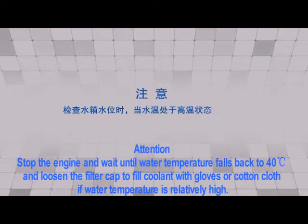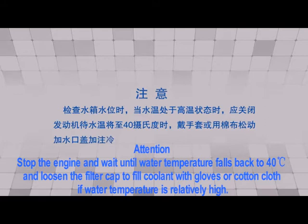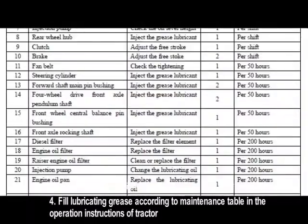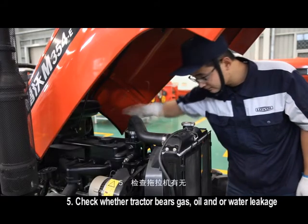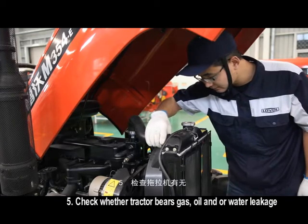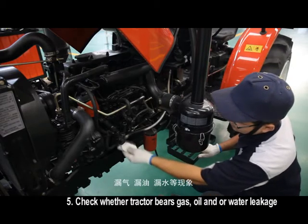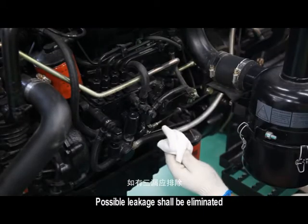Attention! Stop the engine and wait until water temperature falls back to 40 °C, then loosen the filter cap to fill coolant. Use gloves or cotton cloth if water temperature is relatively high. 4. Fill lubricating grease according to the maintenance table in the operation instructions of the tractor. 5. Check whether the tractor has gas, oil, and water leakage. Possible leakage shall be eliminated.